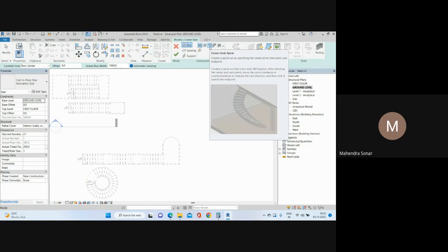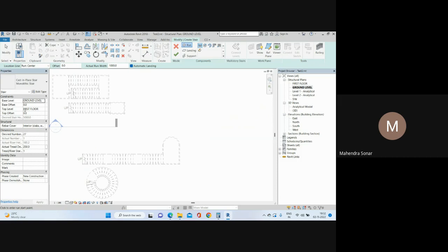On the basis of that it can add this tier. If you want to add multiple levels, you should go with level to level. So if you want to add ground to first floor, you need to add that, then after that first to second, second to third. Okay, but you can give only two levels, base level and top level. Okay, so I have given them here, and on the basis of that it has calculated 27 steps, so total is 5 meter difference.